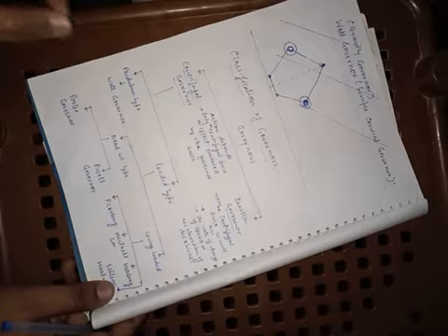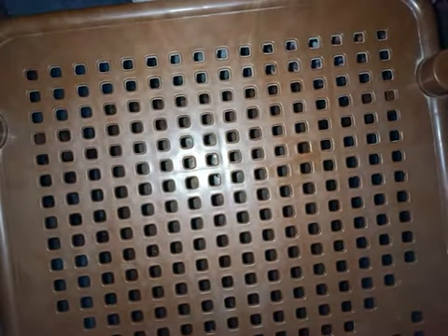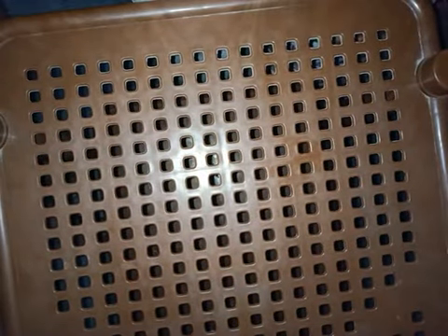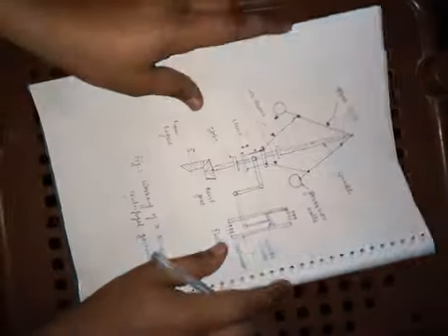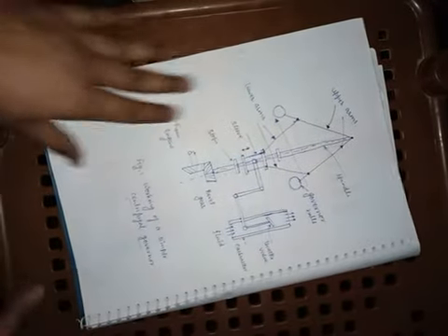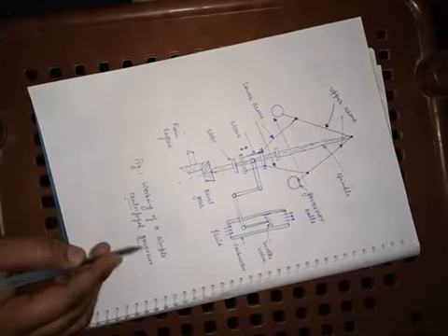This shows how a simple governor controls the throttle. This is a simple working of a simple centrifugal governor, the Watt governor in this case. The basic components of this governor are these two arms, called the upper arms of the governor.